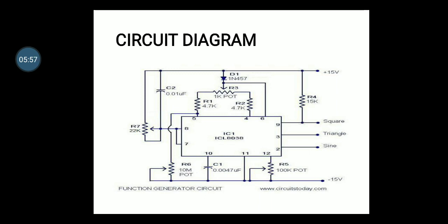For equal magnitudes of current IA and IB, output waveforms are symmetrical. Conversely, when the two currents are unequal, output waveforms are asymmetrical. By making one of the currents much larger than the other, we can get a sawtooth waveform across the capacitor and a rectangular wave at the output of the flip-flop.